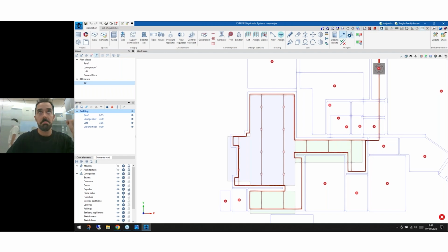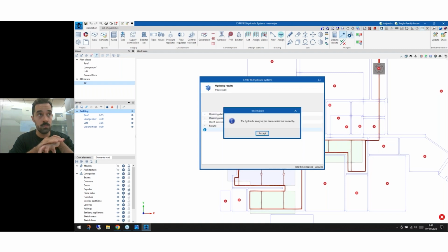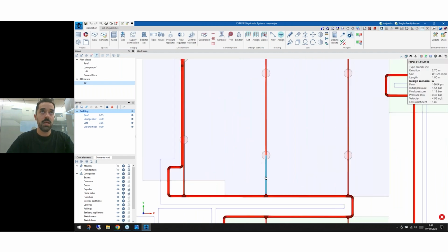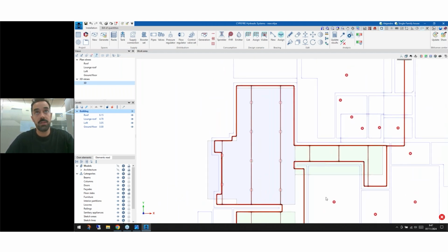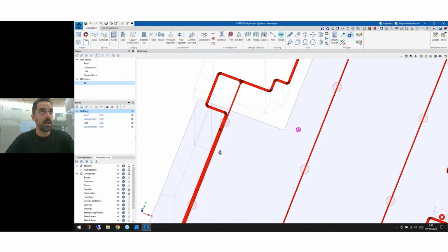So I'm gonna click here and select this design option. Everything has been done correctly. Remember that I selected 2 inches for the cross main and 1 for the branch line. If I go now, the branch line didn't change, and the cross main didn't either. So it's perfect. It's nice to see that in my first design I made it as the software would do it too.